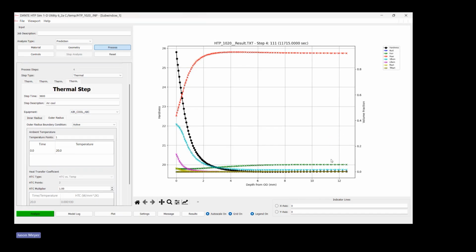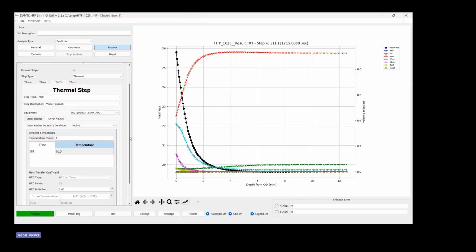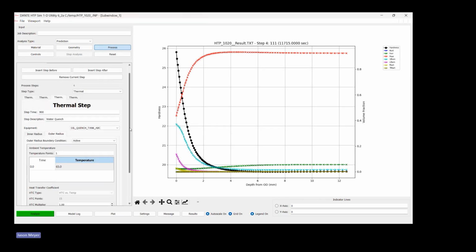So if that's what you were looking for, then this would be a good application. Or if that doesn't meet your requirements, you'd have to look into a couple of other changes, like quenching temperature, that have larger effects. Again, you can go through and look at the multipliers with agitation rate and so on. There's a lot that you can do, and with these little modeling tools, you can really knock out the initial work and then see very quickly what quench rates will work really well for you and your application.